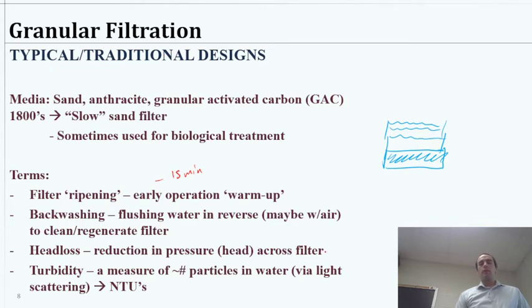Usually we're going to talk about this in terms of the height of the water. So if in a filter bed like this, we have some height where we started up here. So height in meters. And over time, let's say we would probably start here. It only takes a little bit of water. And then over time, the filter gets clogged up. It requires more pressure to put on top of it.